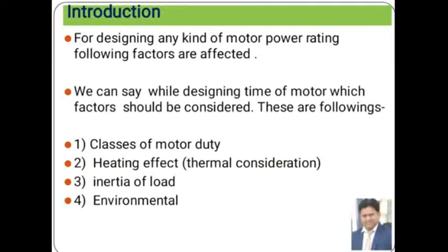Second, if we select a lower rating, what will happen? There will be chances of overloading, it requires frequent maintenance, and the productivity and reliability of the motor will decrease.